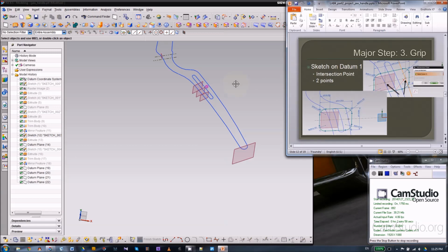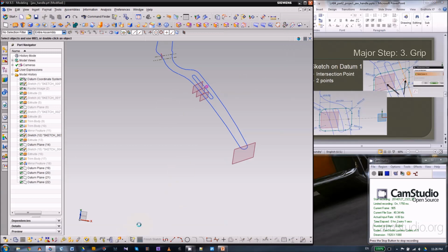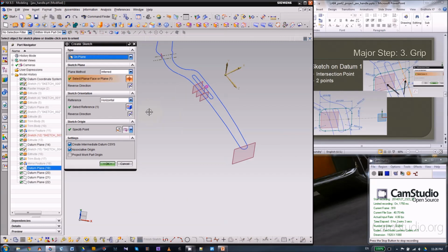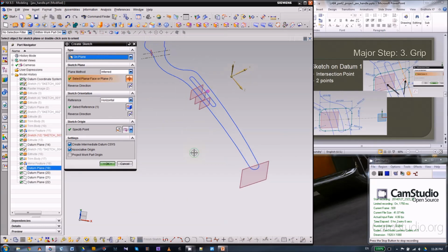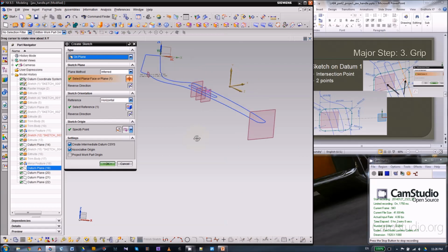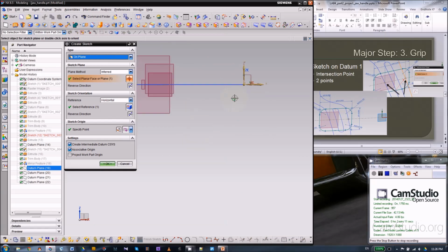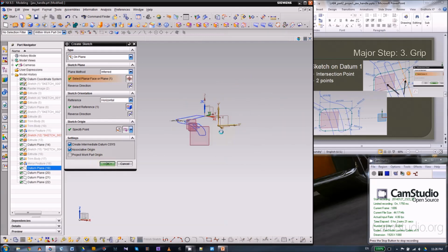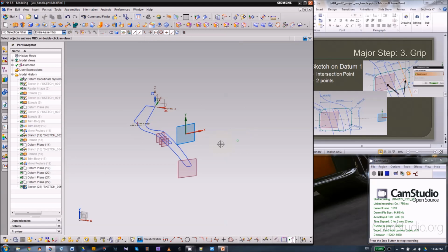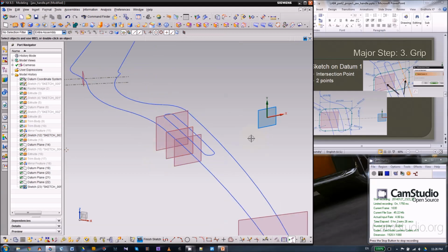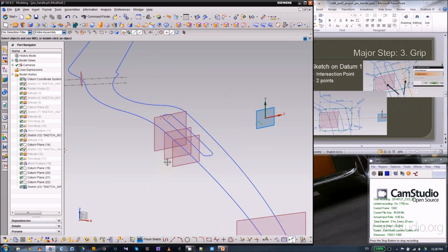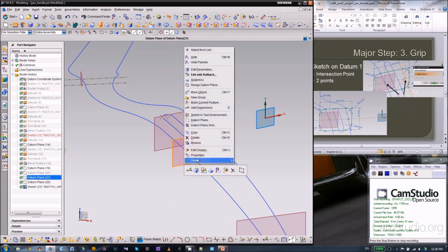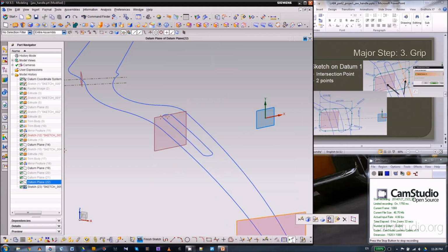So we're going to start the sketch. Now let's first build this sketch, and I'll just leave this coordinate system where it is by default, and just check if this one is actually aligned with the x-axis, the absolute x-axis. Okay. All right, and for this kind of sketch I do want to draw in a 3D view, and we can hide the datums we're not using yet.